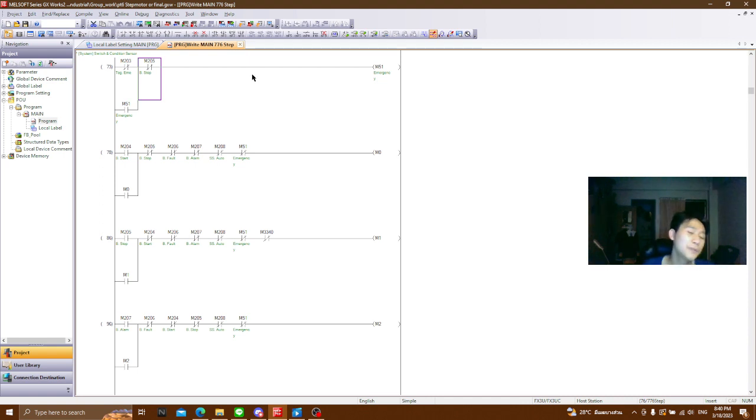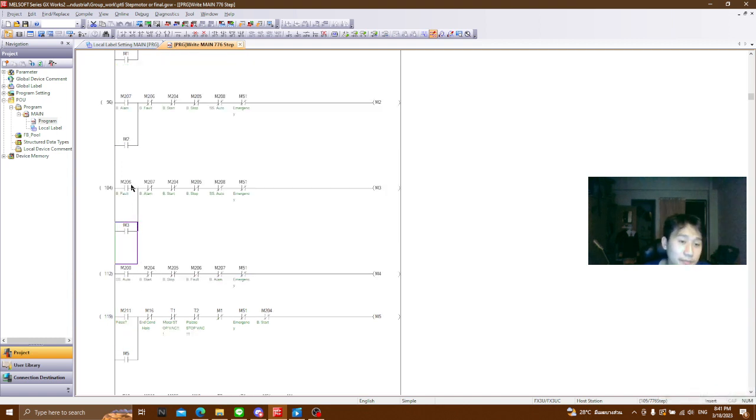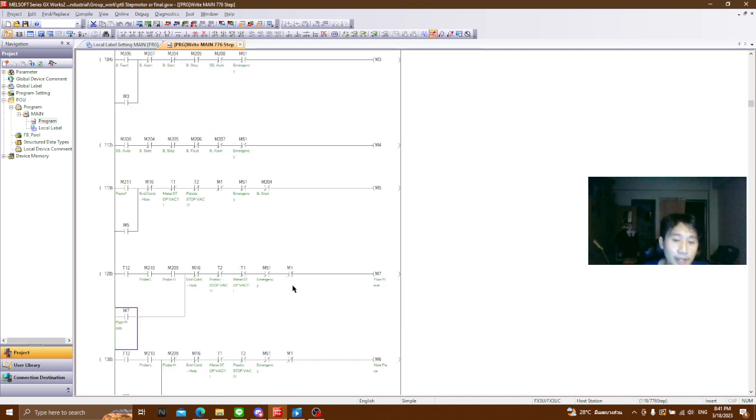But if you push the stop button, it will reset. After you pull out the emergency stop and push the stop button, it will reset all the work and return all the objects or components to home position, and you can press start right here. And also same as the auto switch, button align, button false, subswitch auto is like a toggle switch, so we don't have to create a self-hold. And now are the conditions.